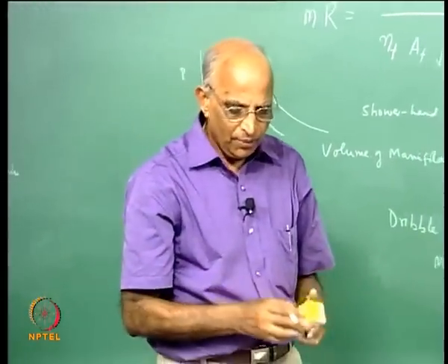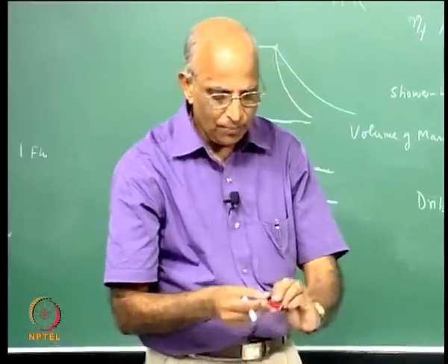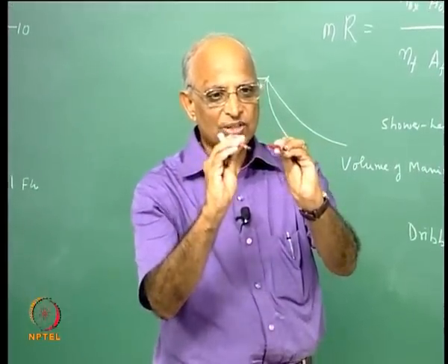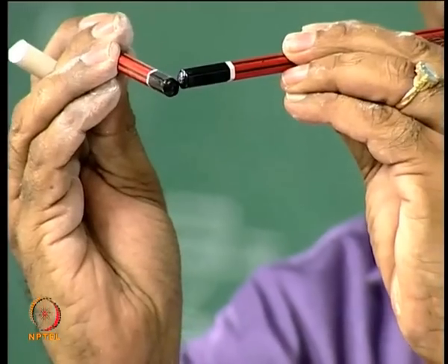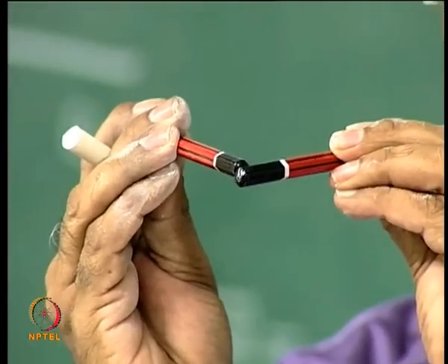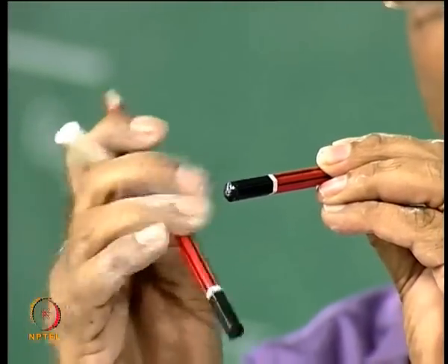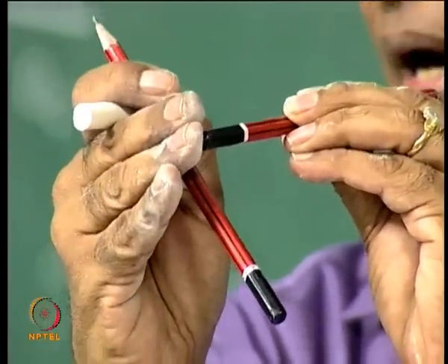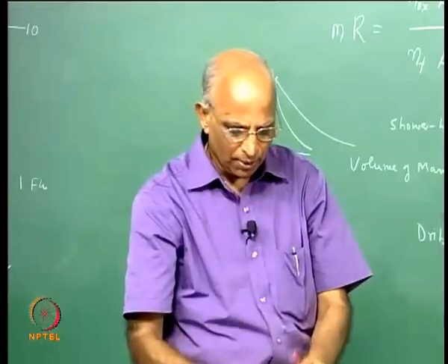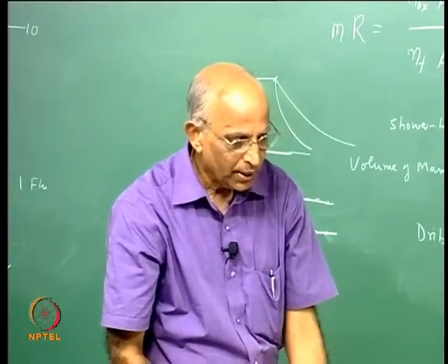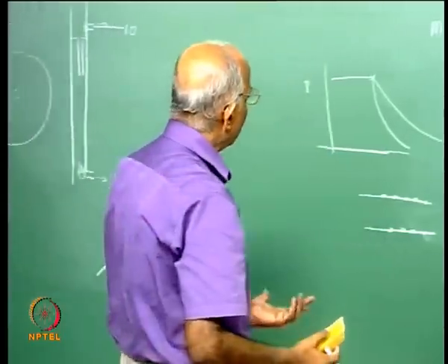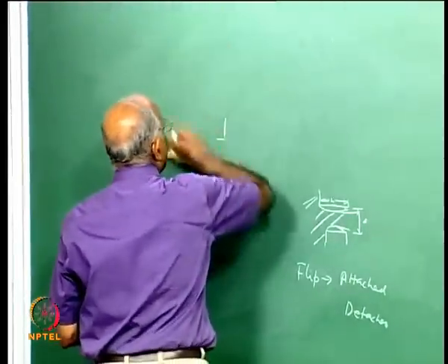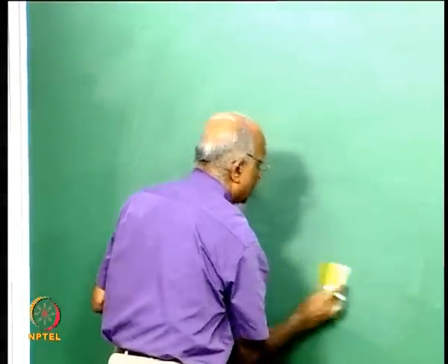What is it we do? Let us say one stream of jet comes like this, the other stream of jet comes like this. Instead of having these jets coming like this, we make them interact with each other. That means we have impinging jets, and once you impinge the jet, you have something like a fan formed over here, and that becomes a thin fan, and that is what begins to burn. Maybe we will look at the different injection devices in the next class, and during that class we will also look at some of the problems which we face in the combustion chamber.